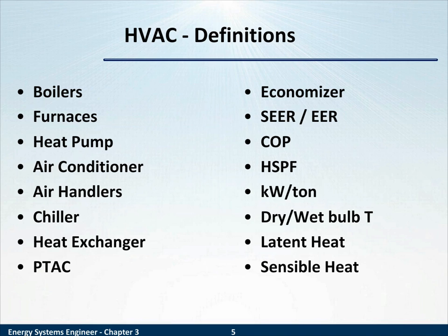The SEER, Seasonal Energy Efficiency Ratio, or EER, Energy Efficiency Ratio, these are ratios of heat extracted to energy input. The SEER is a testing protocol that takes into account that most units experience their operation in different seasons. Although we don't go into detail, the SEER testing protocols assume a certain kind of season. However, do indeed all locations have the same seasons?